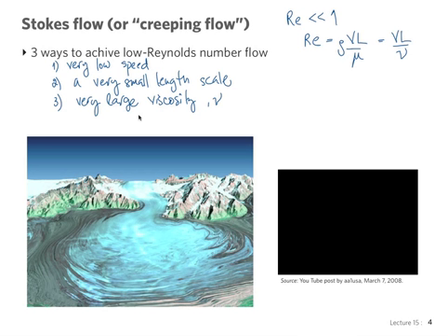And for each situation, people have observed experimentally when what we call transition to turbulence occurs. But anything in the order of thousands and 10,000, we consider moderate Reynolds number, but in the pipe flow situation, it will be turbulent, even though it's a moderate number. High Reynolds number, when people talk about, for example, simulation at high Reynolds number, they usually mean 100,000 to millions.